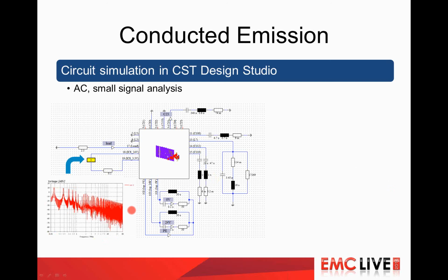Okay. Could cables be included in the models? Yes. So I did not talk about cables in detail, but we have a tool which is called CST Cable Studio, which offers advanced functionality of modeling cables where you have a hybrid approach in including cables and also being able to calculate complex cable cross-sections and also shielded cables and so on. So this was not part of this webinar, but this is possible.